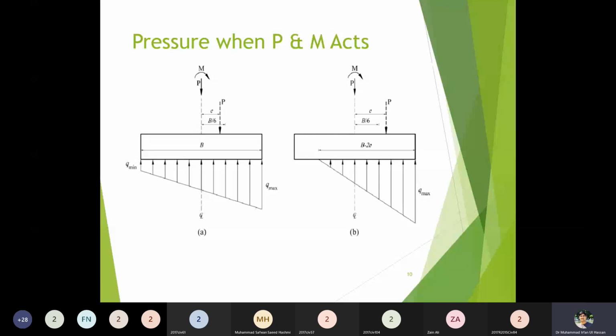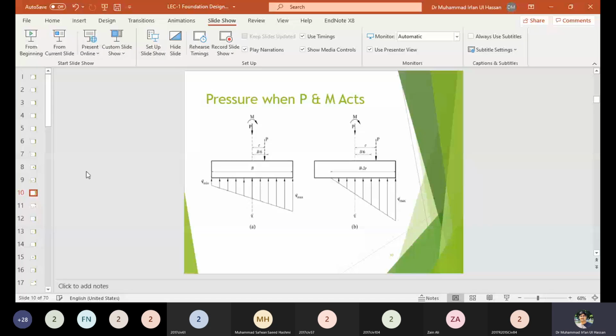Footing को हम कोशिश करते हैं कि compression में हो सारी, जैसे left hand side वाला हो, but when the pressure is tensile or negative, तो एक तरफ pressure नेगेटिव में चला जाएगा, बट इफेक्टिव पार्ट हमने वही लेना है जो कंप्रेशन में हो। जैसे राइट हैंड साइड है तो एक्चुअली उसकी डायग्राम तो डिफरेंट बनेगी। ये प्रेशर जो आपके पास बनेगा,